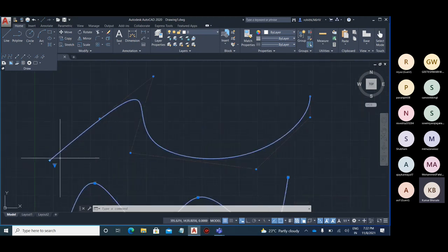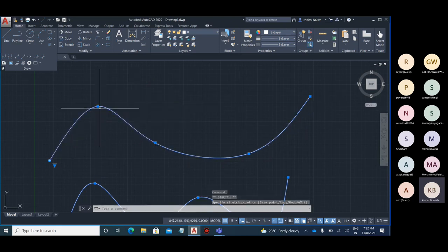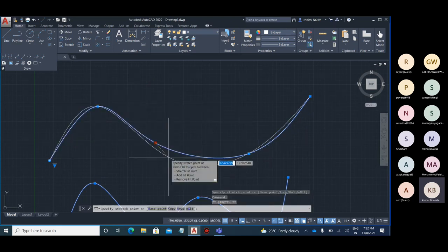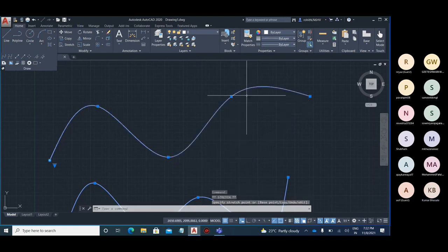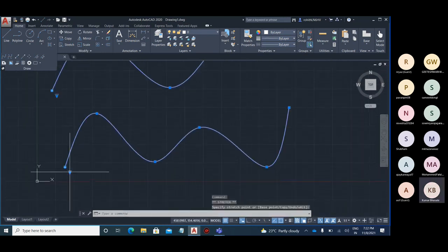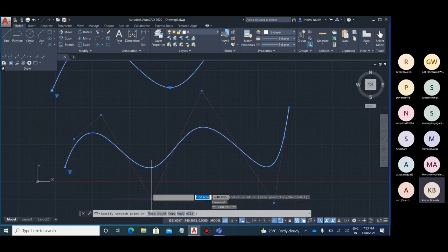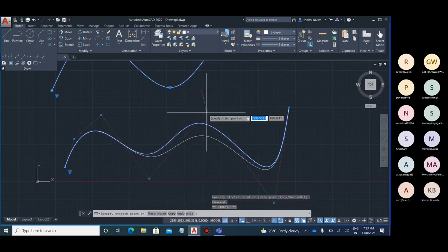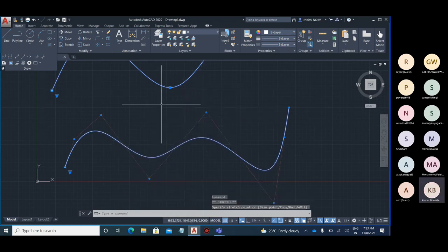Now, of course, a spline CV, that is spline control vertices, can be converted into spline fit. Just hover on this arrow and click it. You can see over here fit, and you can see the points are now on the line. So this is how it can be changed. And if you come down over here, the same spline fit can be converted into control vertices, and you can just select and bring this up and down. So this is your spline control vertices.